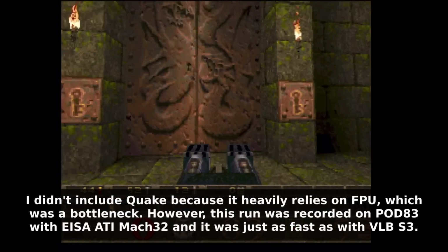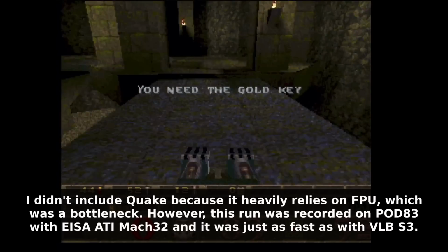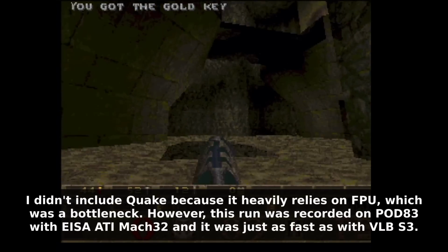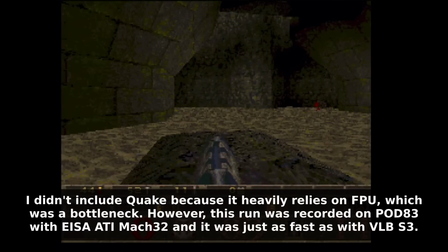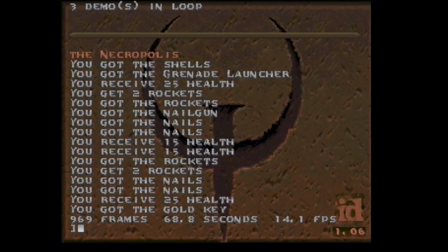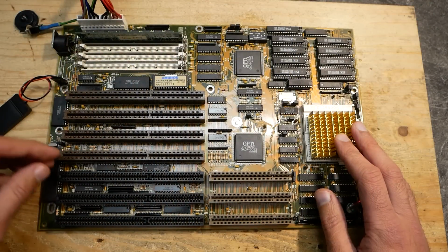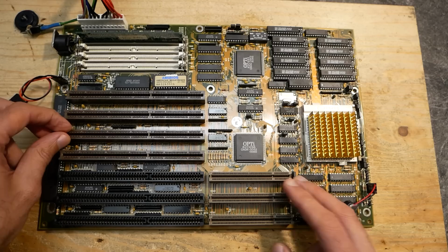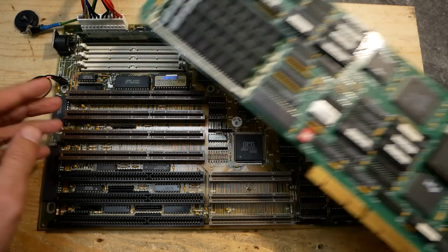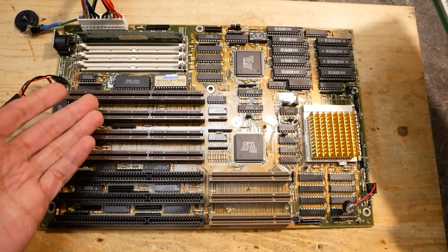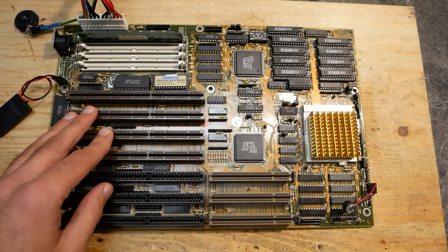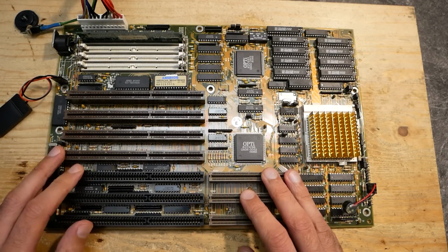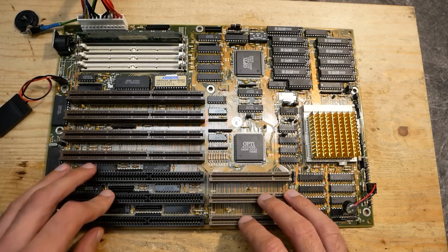So gaming on an EISA system is probably not quite as exciting as it might look at first glance, and another type of benchmarks would be more interesting. Still, I think this board is interesting even for gaming because it has a VLB slot. With a fast VLB graphics card, it would perform nicely in games, and with EISA controllers and network cards, it would scale much better under heavy I/O compared to ISA. I guess I will have to plan more tests under Windows and, as I said, see which benchmarks could really bring EISA to shine against ISA.